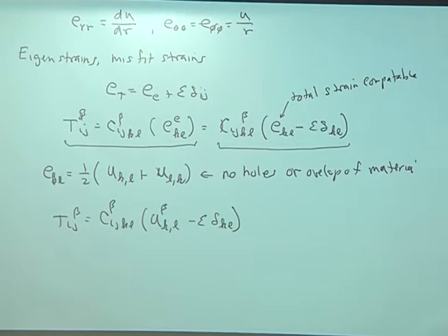So the factor of 2, where did the factor of 2 go? I think I heard someone mention that. It has to do with the symmetry of the elastic constant tensor, because these are implicit summations, so you can interchange K and L. If you substitute this into here, you see you're just interchanging L and K. So you basically lead to the same term. They sum together, and the 1/2 disappears, and you can write it like that.